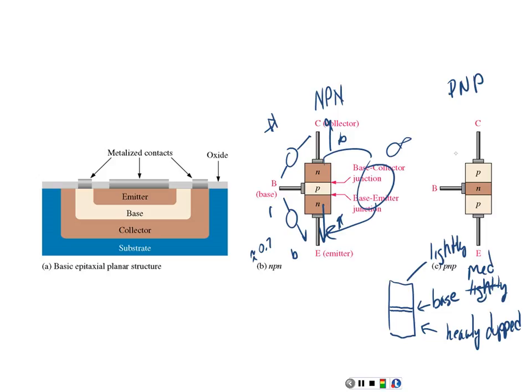So we check these just like we do a diode. We forward bias and flip it around and make sure that it doesn't measure the same in both directions. It should measure real high in one direction and real low in the other if I'm going between the base and the collector, right? Understand? Then I come over here and do this, and make sure you swap your leads around just like you should on a diode, right? You understand? Because it is supposed to measure low on one side and high on the other.